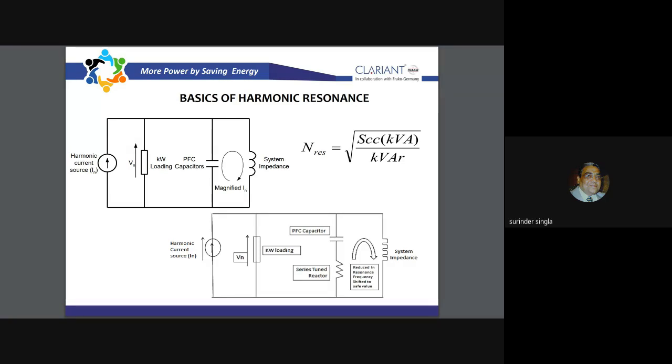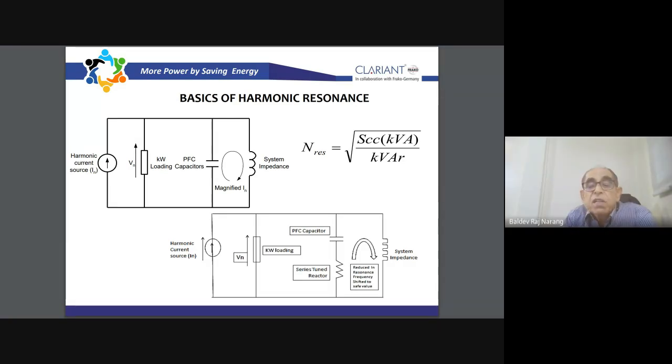What about voltage harmonics? Voltage harmonic is, whenever you have a current harmonic generated in the system, suppose we have a load. And that load will be having non-linearity. It will draw a non-linear current, and then it will have harmonics, and that harmonic will travel towards the source. And during that process, it is encountering some impedance. So suppose for the load 2, it goes to the LT bus. So LT bus, it will experience some voltage distortion because of this.